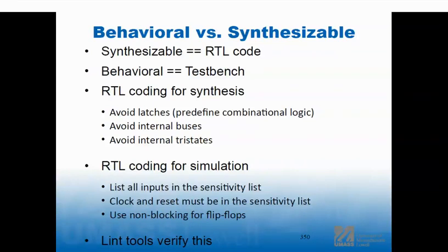But in simulation, we still have some things that we have to do, right? It still has to have at least an interface to the DUT that looks like a digital system. So we're still going to use the kinds of constructs that we use to drive the DUT and receive things from the DUT. But everything inside that, we can use constructs where we don't have to worry about clock edges per se. We don't have to worry about big math things. We don't have to worry about not using floating point and those things that would really not be synthesizable.